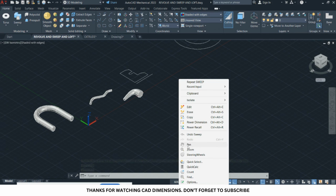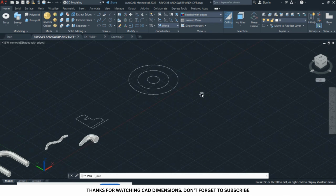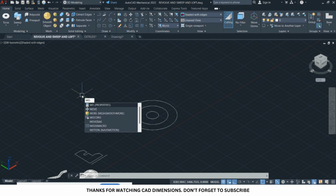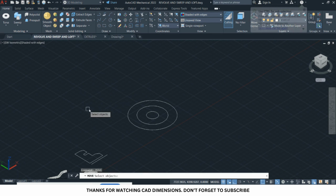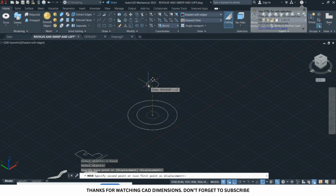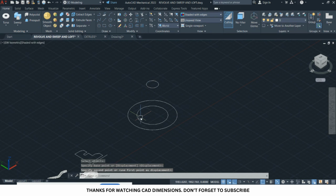Let's move to the next one, which is the loft, and then we bring the lesson to an end. For the loft, you need to create plane shapes in different planes. Currently they are all in the same plane, so I'm going to move them. I'm going to move this, press enter, and move it up a little bit so that it is in a different plane.